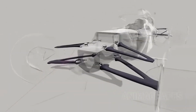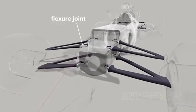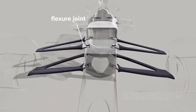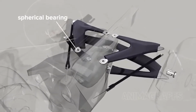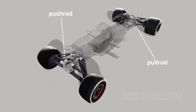At the front, where heat isn't an issue, wishbones are directly attached to the monocoque and have simple flexure joints designed to bend under load. At the rear, where engine heat can be intense, spherical bearings are used. The push or pull rod is where the action happens.